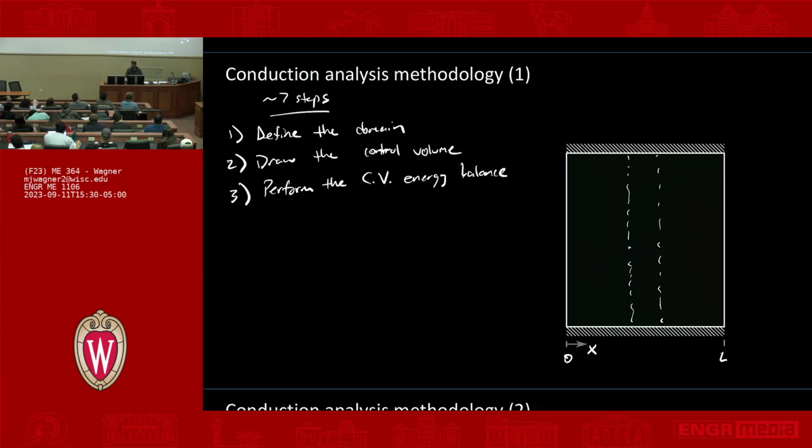So first of all, from the left-hand side, I might have heat flowing in, right? We would call that Q dot, and let's say that Q dot is at the boundary x, at some coordinate x. I might have something leaving, right? I can't have anything leaving from top and bottom. Those are adiabatic surfaces. But I have something leaving from the right-hand side. So let's maybe come back to that name, but you can have that leaving.